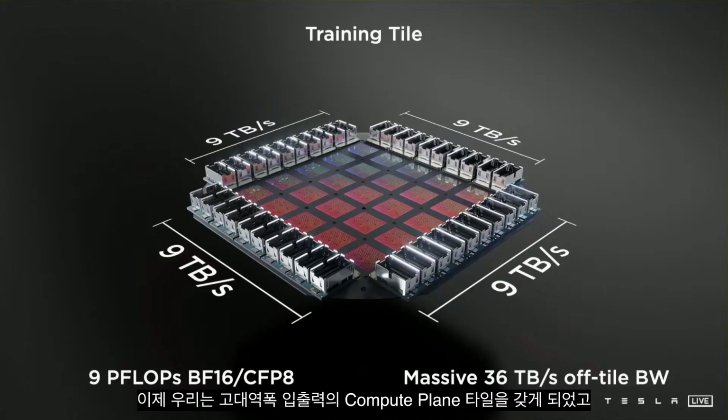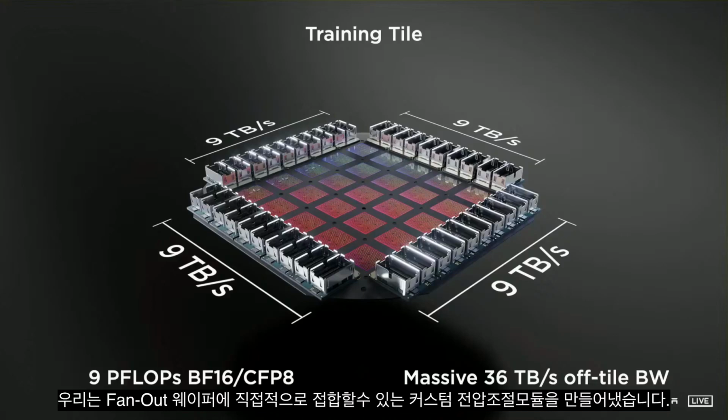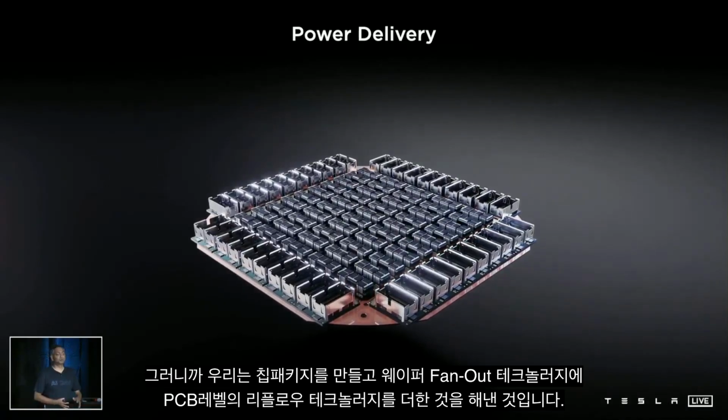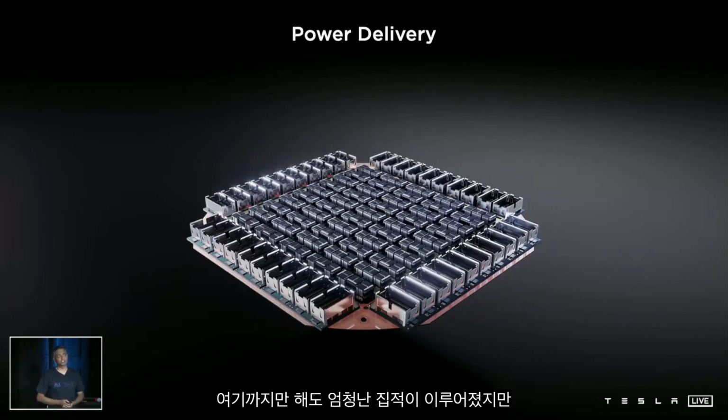Now that we had our compute plane tile with high bandwidth IOs, we had to feed it with power. And here, we came up with a new way of feeding power vertically. We created a custom voltage regulator module that could be reflowed directly onto this fan-out wafer. So what we did out here is we got chip, package, and we brought PCB-level technology of reflow onto this fan-out wafer technology. This is a lot of integration already out here.